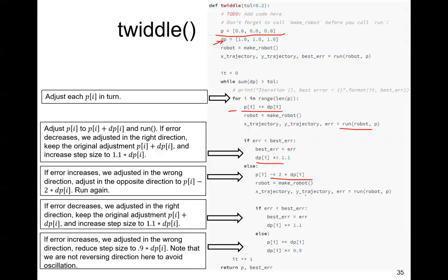And then yes, can I have a little bit of comment on this as well? Sorry, and that is if you work with control, if you start with a p-value, the proportional part, and it works okay. But then when you add an integral part, you have to reduce the proportional part to keep stability in a control system. You can't select the best p with the integral part at 0, because when you increase the integral part, you have to reduce the proportional part.